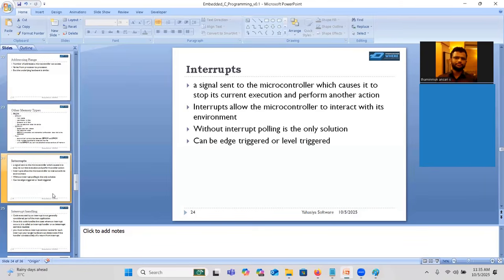What it will do is, in the program counter, it will load an address, a program memory address. What is that address? In some microcontrollers, they have a list of addresses, one address for one interrupt. Let us say for the serial port interrupt, they have assigned program memory address 5. If a valid character is received from the laptop or PC to the receive register of the microcontroller, the program counter will be loaded with program memory address 5.